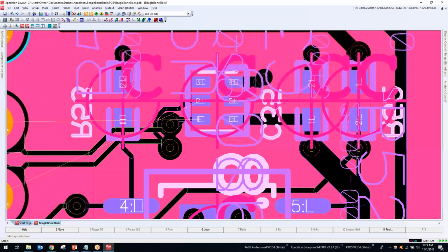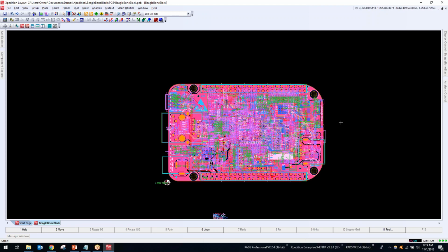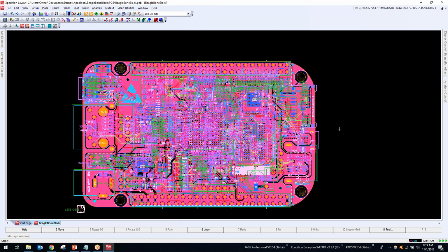All right, so what we've done so far is we've placed and routed this board. We've run some HyperLynx DRC rules. We've run some HyperLynx PI rules. And then we actually ran some Valor NPI rules for manufacturing checks. All right, so that was all I was planning on showing you today.